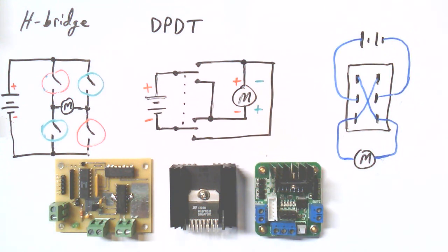And then if you think about it, you can use pulse width modulation on that enable to control the speed of the motor. So that's the kind of functionality that you would see start to build into some of these full motor control type ICs. A lot of times speed and direction can be controlled, and it's the same for stepper motors too. We'll get into that. That's a whole different type of control. But again, these ICs can do that as well because of the switching.